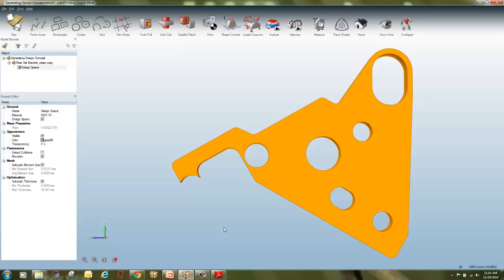Then orthographic and perspective projection. In Inspire there are two basic methods of displaying 3D objects on a 2D plane: perspective projection, which takes perspective effects into account, and orthographic projection, which does not take the effects into account. Most of the time you will want to view your model using perspective projection, which shows distant objects as smaller and close objects as larger to provide great realism. Orthographic projection, on the other hand, is useful when you want to create scale drawings with accurate measurements and proportions.